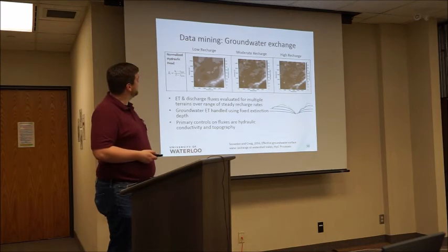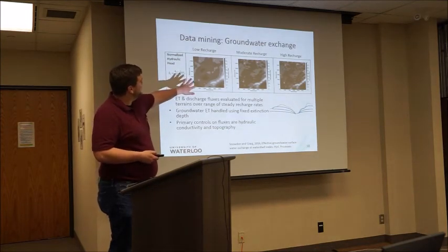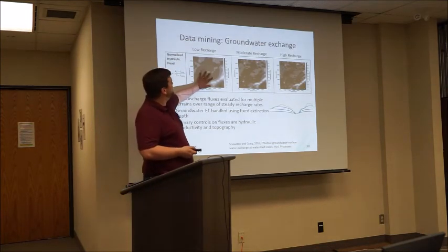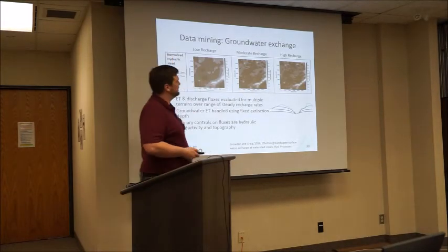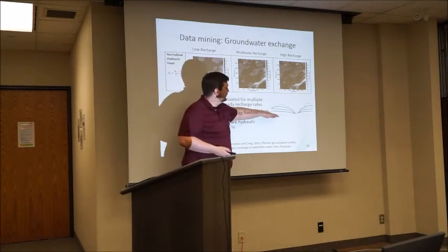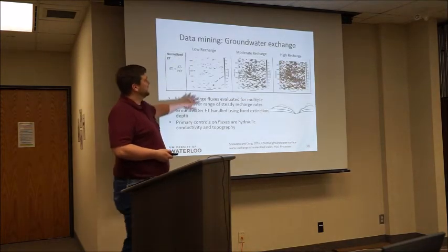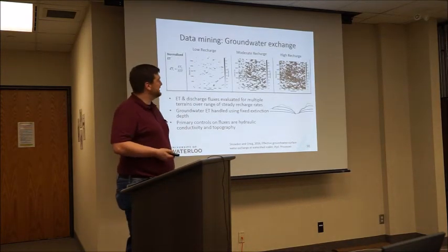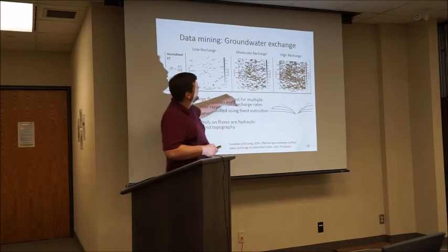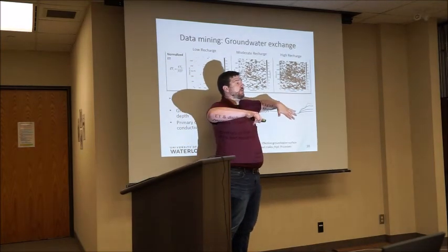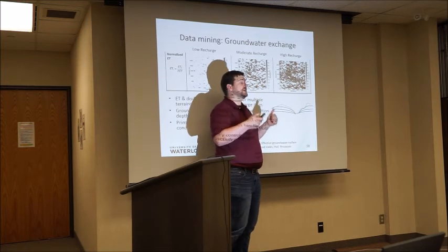So we took a hummocky terrain. This is the normalized hydraulic head for a low recharge case, moderate recharge case, and high recharge case. So this is basically looking at all those various different states, looking at the head distribution. We can look at the ET distribution as well, groundwater ET. As we raise the water table, higher recharge cases are going to have a higher water table, and more water is going to evaporate to the atmosphere.